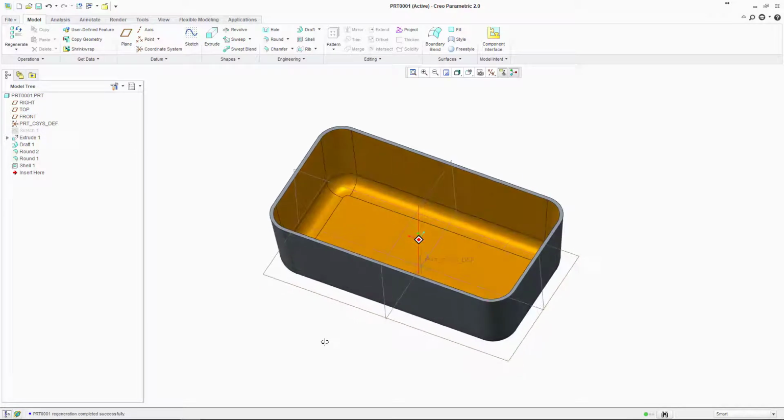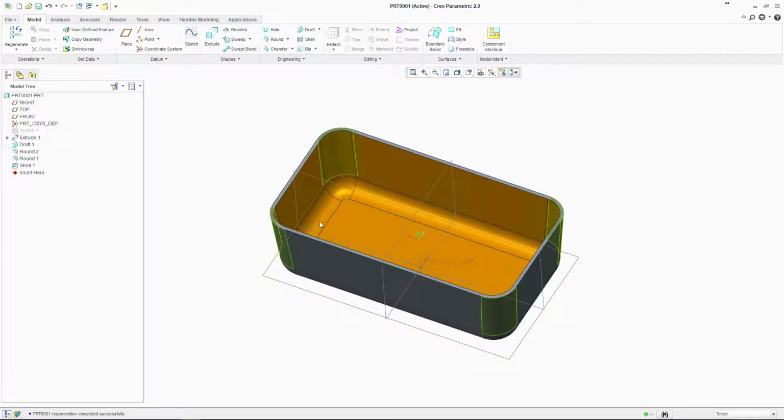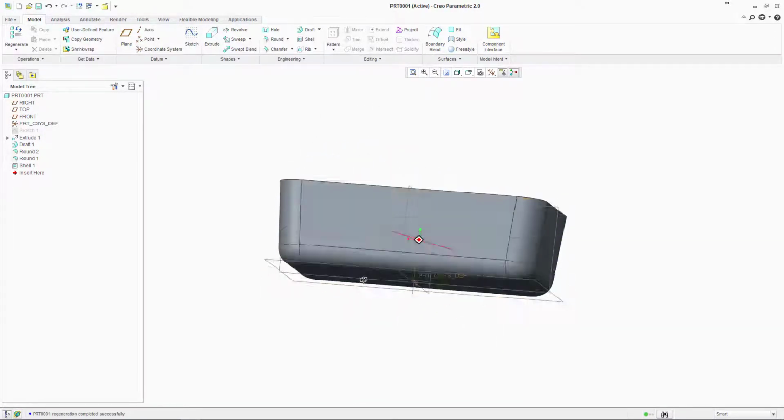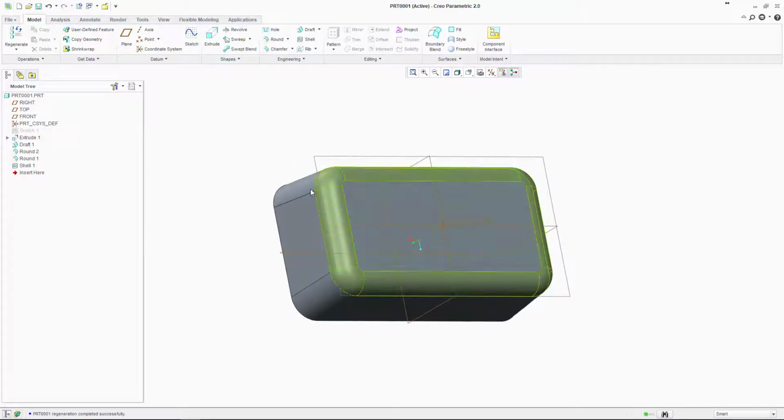So maybe this would be a plastic, maybe polypropylene or polyethylene, and you made it using the injection molding technique. And most likely what you would do is you would machine an aluminium mold out of two pieces of aluminium, and one piece would fit inside this shape here, so it would essentially be a protrusion, and the other half of the mold would have an indent that would surround this side of the part.